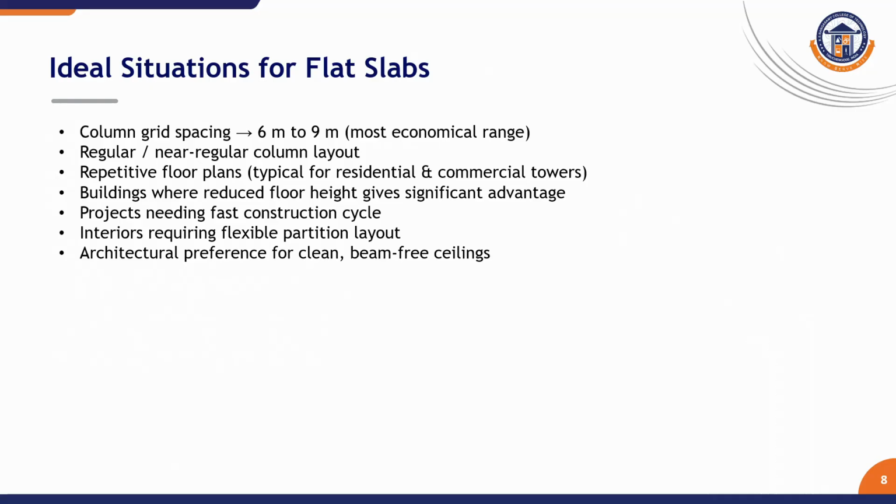Flat slabs are most suitable when the column grid spacing is between 6 meters to 9 meters, the column layout is regular or near regular, and floor slabs are repetitive, typically in towers. They are also suitable when reduced floor height provides significant advantages, a fast construction cycle is required, a flexible interior layout is needed, and architectural performance with a clean, beam-free ceiling is expected.